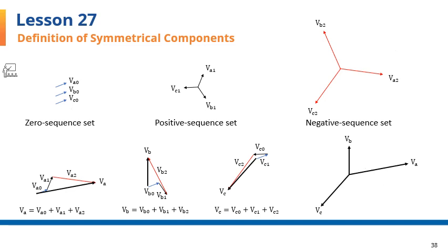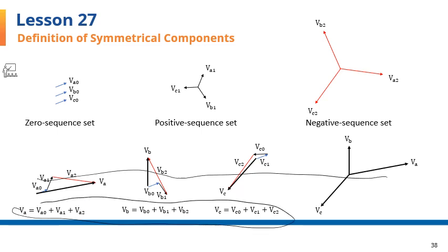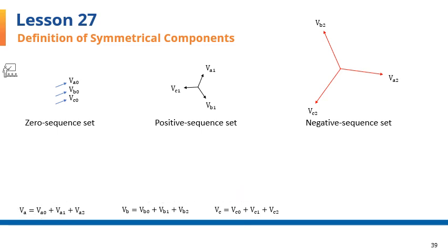This process is best explained with a little bit of algebra, so I'll delete the diagrams that we have here and keep the equations, these 3 equations. I would like to introduce a constant complex number with a magnitude of 1 and an angle of 120. This number is useful in this work and typically is given the letter A for its name.